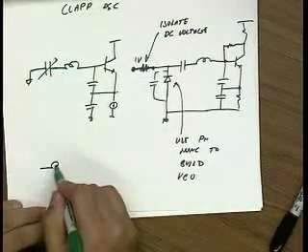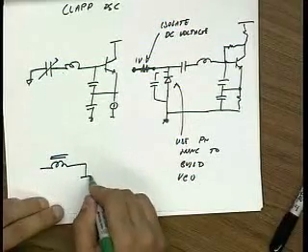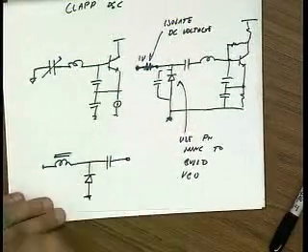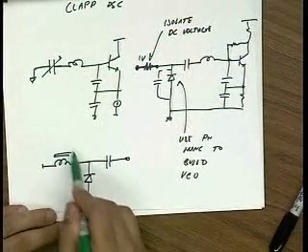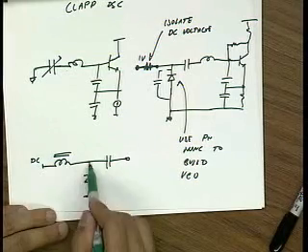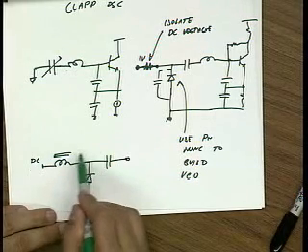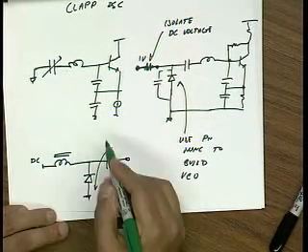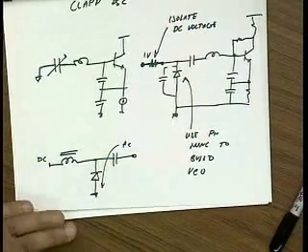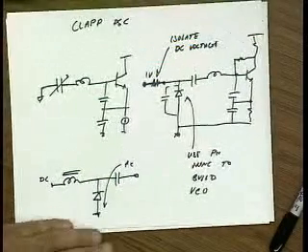Actually it's preferable to use a large inductor, because then the inductor introduces no noise into the circuit and it lets you bring in a DC voltage here, and the AC signals see a high impedance, so all the AC signals will go in this direction. Thank you. Okay, any other questions?